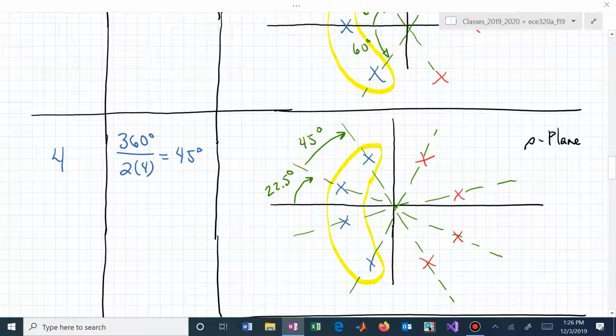They go really, really flat until they get to that break frequency, and then they bend, and then they start zipping down depending on what little n is. N times minus 20 dB per decade gives you the roll-off amount. The Butterworth gives us that nice flat magnitude response in the passband, and then we have that sharp cutoff or roll-off.